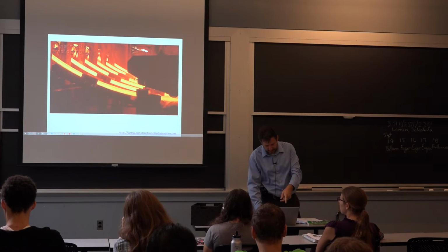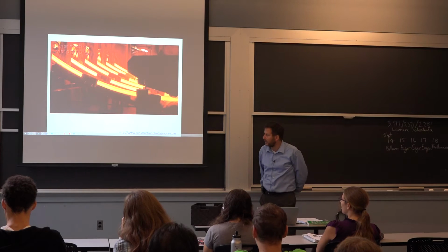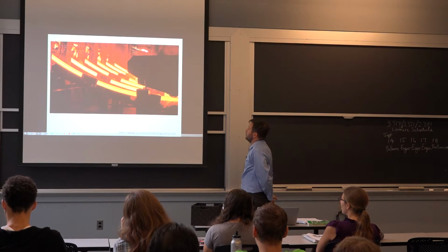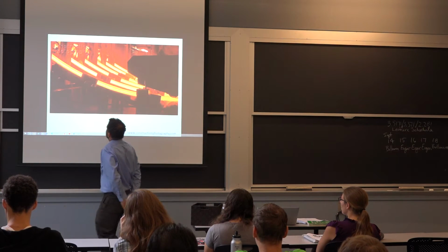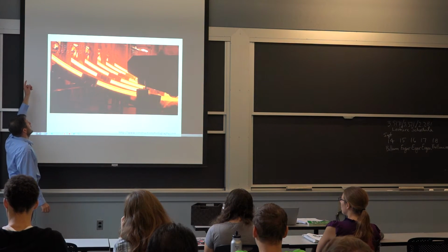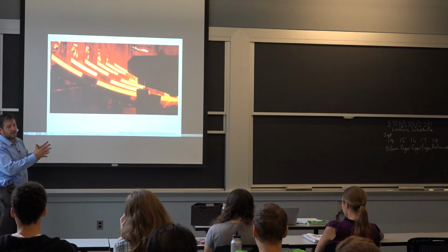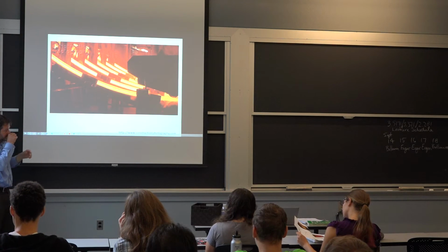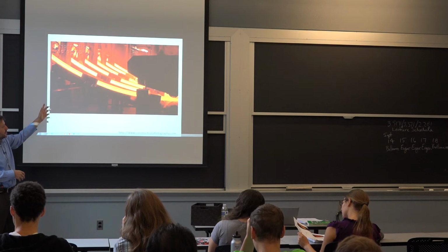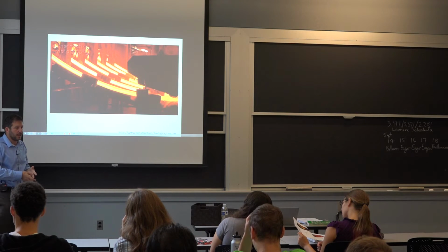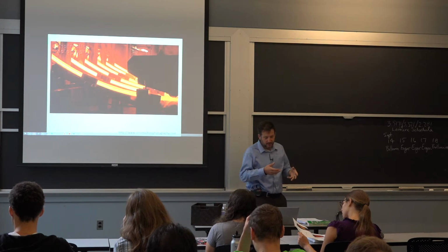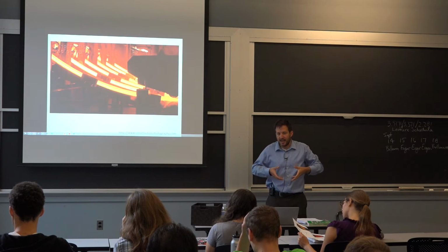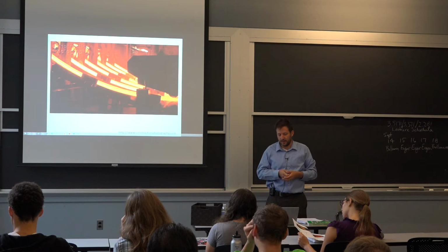So the first step in making that raw product is to make billets. Showing essentially here what is coming down the furnace. So you have the liquid steel that goes into these molds where it's cast, and as soon as it's strong enough, it's exposed to the air to cool it off. You want to cool it relatively quickly so you don't have too much difference between the outside and the inside structure of your billet.